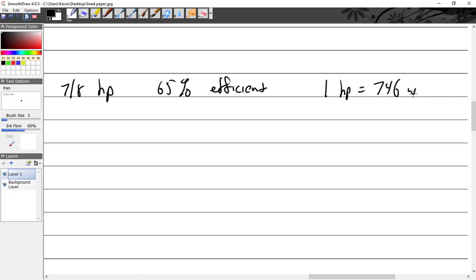All right. So we got to think this through here now. What's the first thing I can figure out? 100%, what's that? 7/8 horsepower. Then how many watts is that? I want to convert this to watts. 746 watts is how many horsepower? 1. Then 7/8, do I want to leave it in 7/8? No. Decimal. What's my decimal? 0.875. Okay.